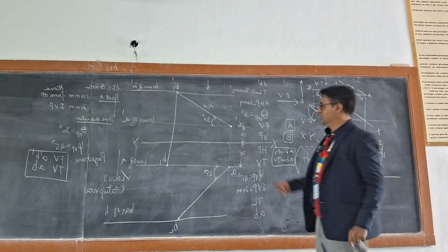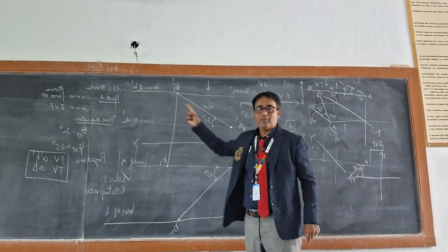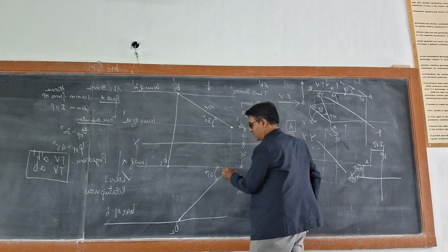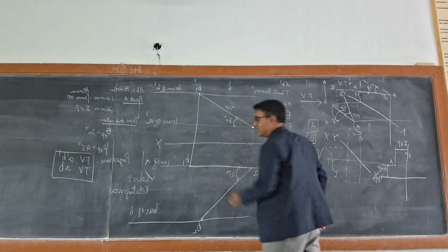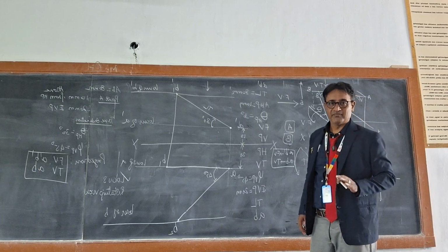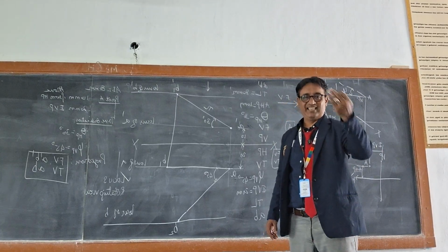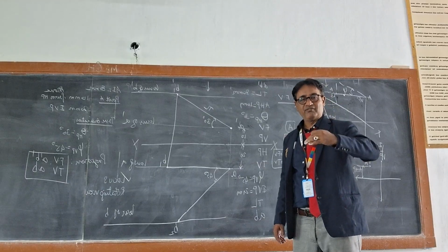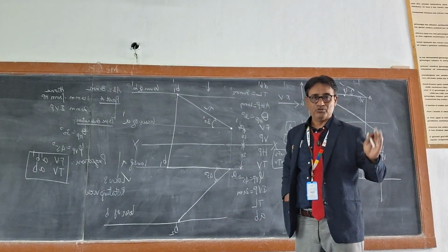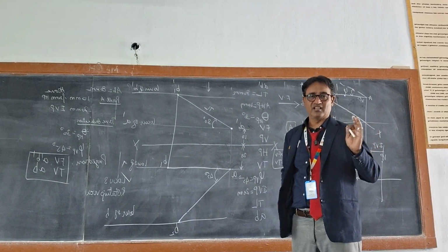Now the logic here is, this true length is measuring 80 mm, but the projection of this inclined line, which is nothing but this line, will have a length less than 80 mm. Meaning, the length of the projection of an inclined line will be reduced. It will be less than the actual length. So that is the logic.